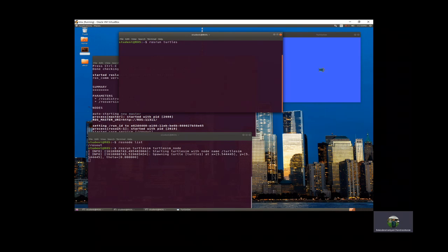So what I'm doing now is typing turtle, and then if I type S, it will auto complete when I press tab, and then we have turtle teleop key, so that I'm controlling it through the keyboard.